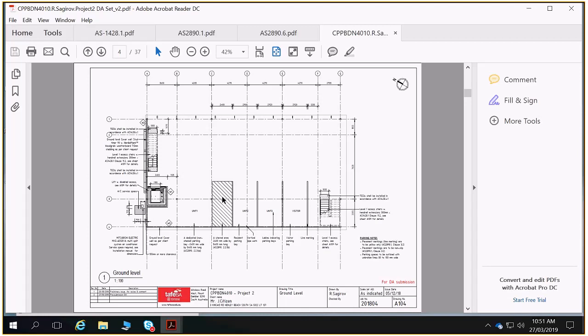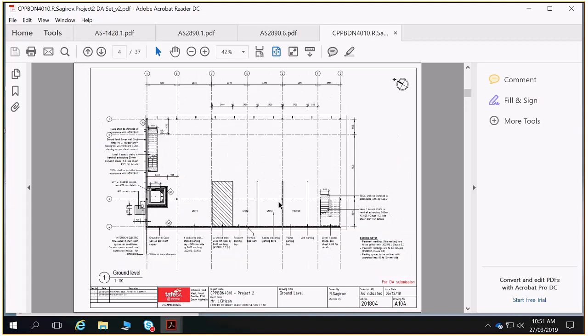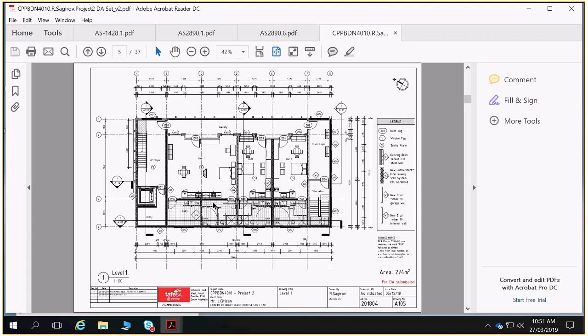If you're going to be messing around with the wall, say that you make this one and you're messing around with that wall, then you've got to transfer loads over to this column here. That's in another apartment there, and that means you're disturbing a second apartment. So beware of those things. It tends to be easier to not disturb that wall too much.